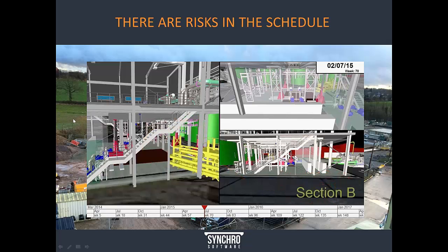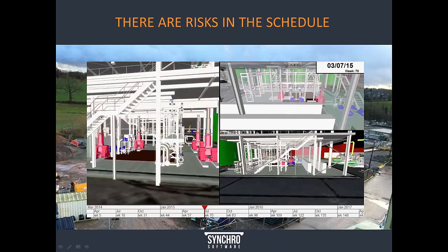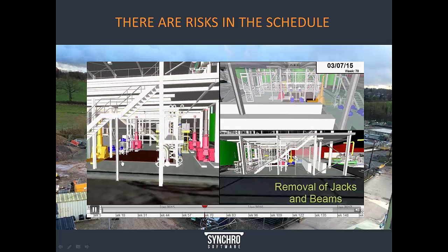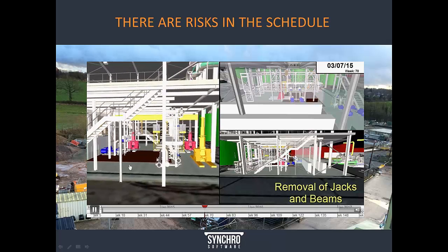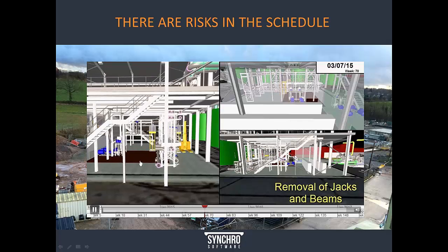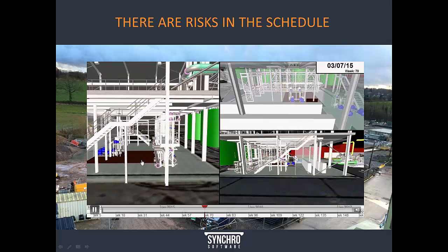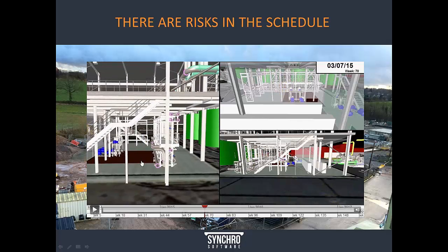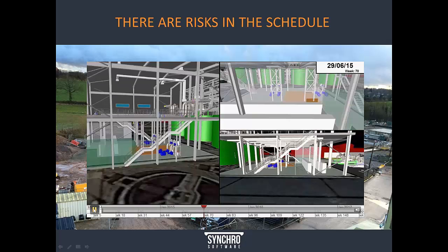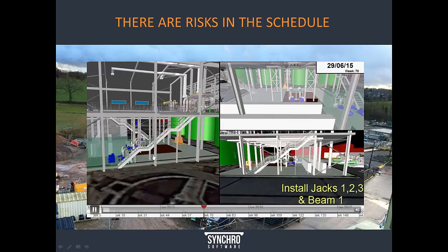And so what happens is you can have the prefabricated assembly delivered to the site and then hit a delay due to the fact that it literally has an obstacle before it can be installed. And this is an issue that's come up in, for instance, a project here in England where the use of Synchro enabled them to digitally rehearse the planning of the installation of the prefabricated assemblies in a manner that ensured that there would be no obstructions during the process.